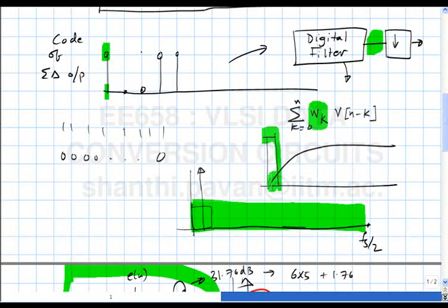And in some filter structures like IIR filters, this is equivalent to overloading if the coefficients or register lengths are finite, it is like chopping off internal node variables so that they cannot go beyond a certain range, okay. So such effects or such errors are called round off errors, alright, and saturation errors.